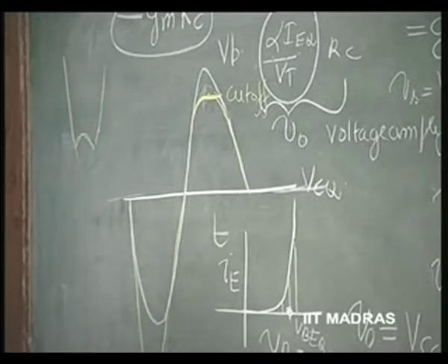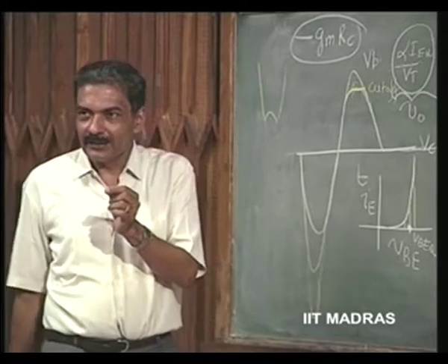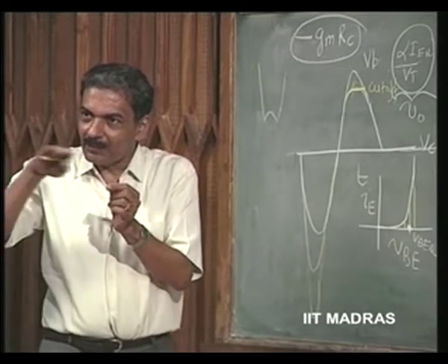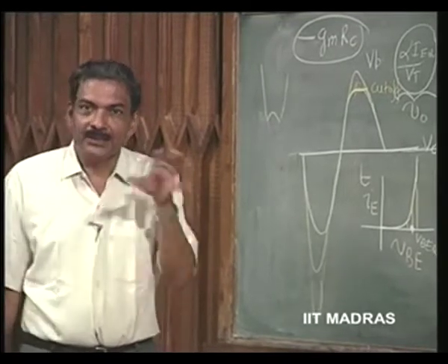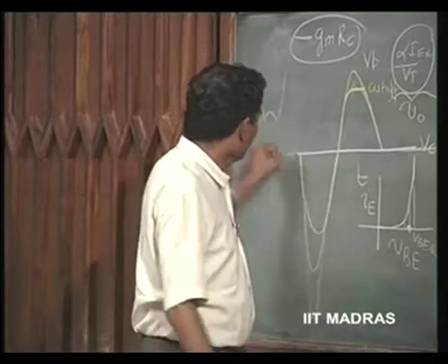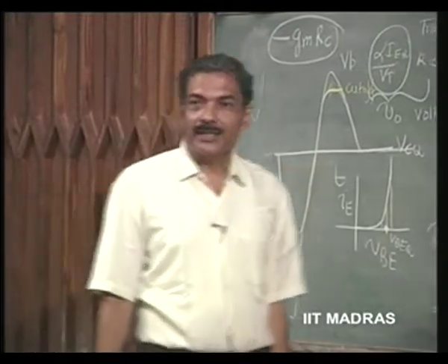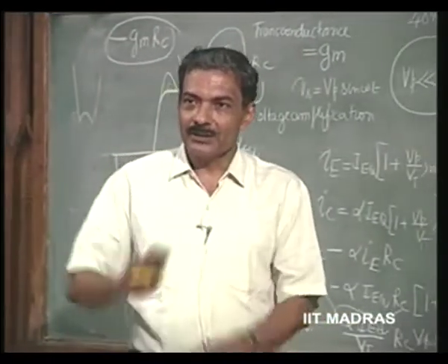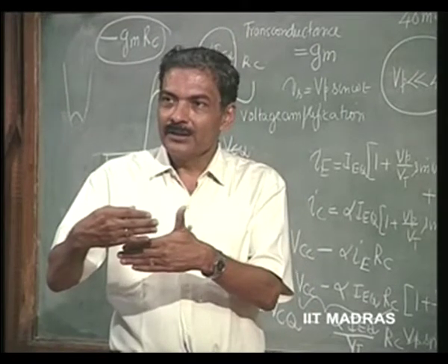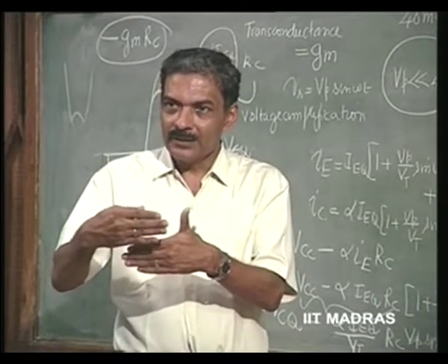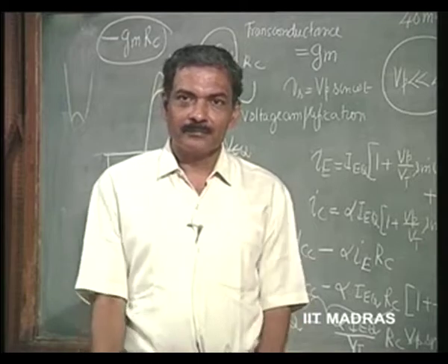So you might not really see that increase there, or it might appear almost flat if it is a good amplifier. If it is a bad amplifier, you will clearly see that it has gone over to saturation, because there is going to be this flip over of this portion of the signal. Is it clear?